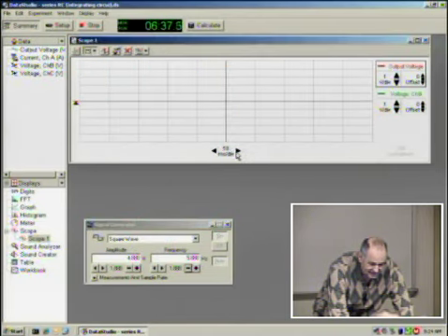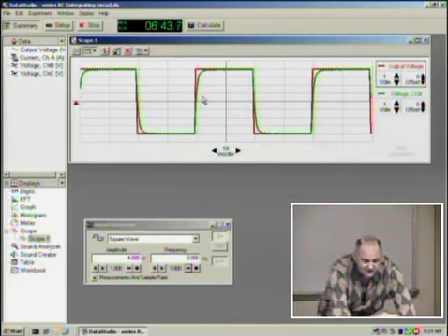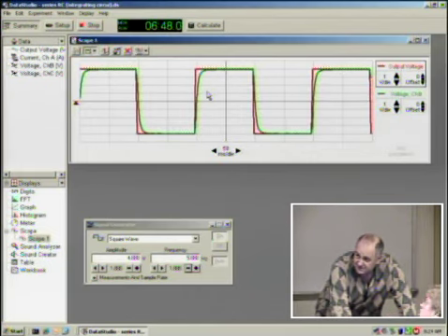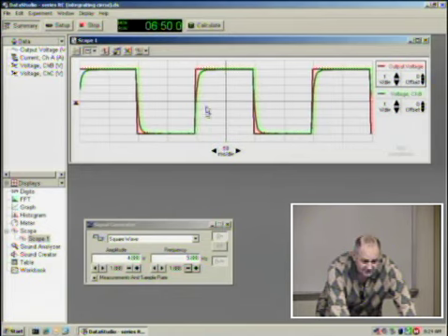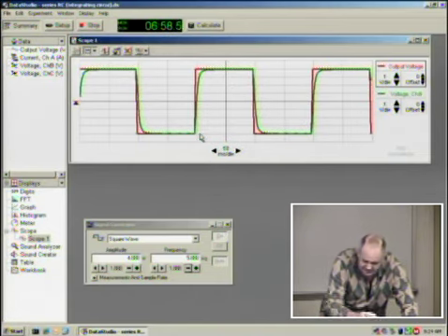Let me stretch it a little bit. So actually you see that because we are missing those frequencies, the output does not resemble the input. In order to really create a square wave, we would have to combine a lot of frequencies. If I miss these frequencies, this is what happens.